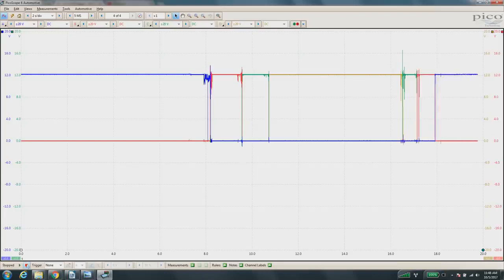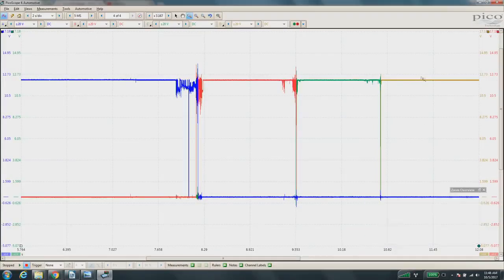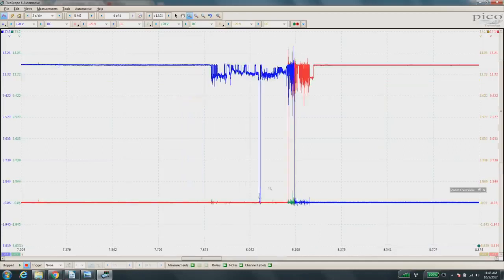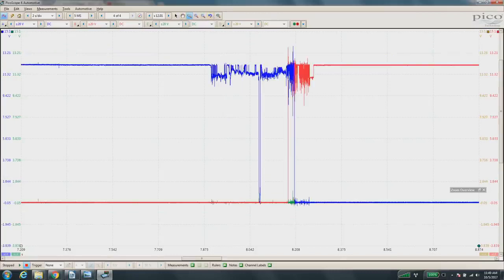Okay, we'll leave it at that, and let's go ahead and zoom in. So here's our event, park to reverse to neutral to drive. Every time our signal goes high like this, we're in our other gear. Let's look at this right here. See how messy this is, guys? This is a signal that's coming out of our transmission range sensor. Okay, look at this. Right here. Is this not the same as telling the computer we are no longer in park?